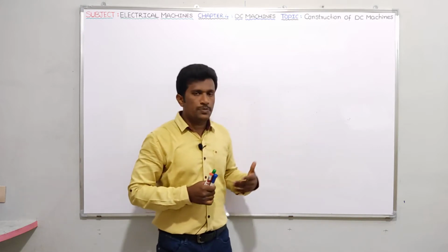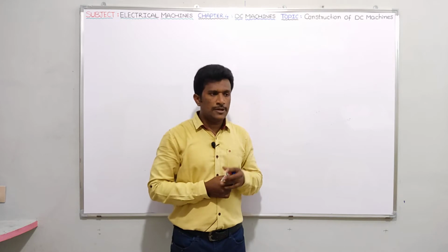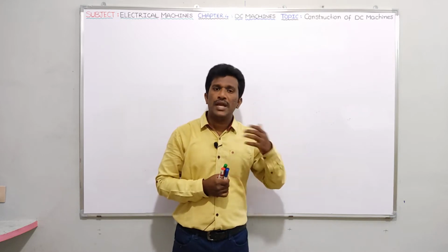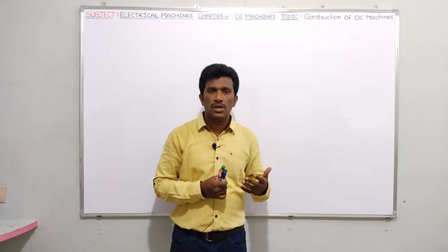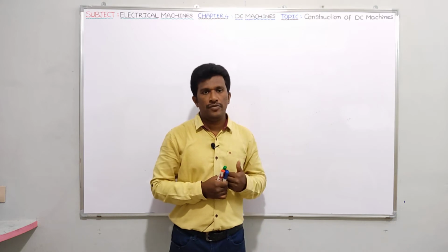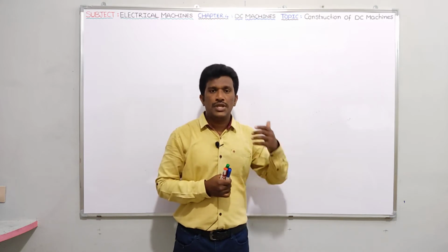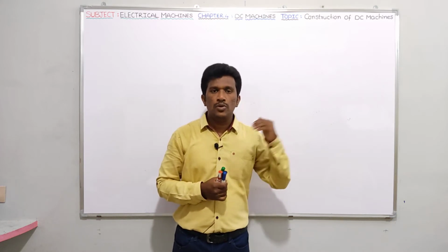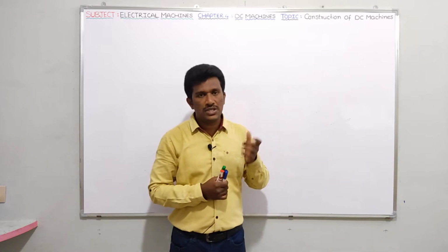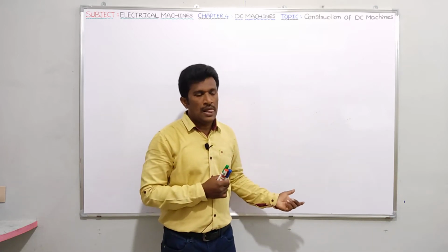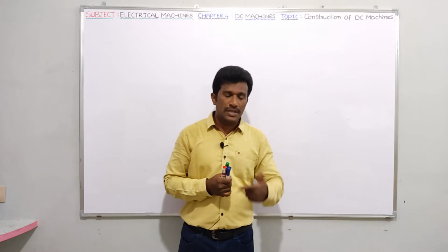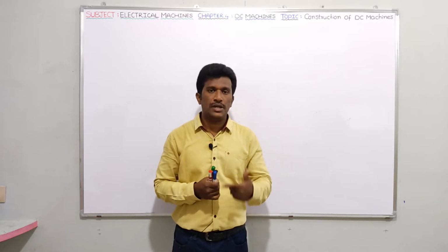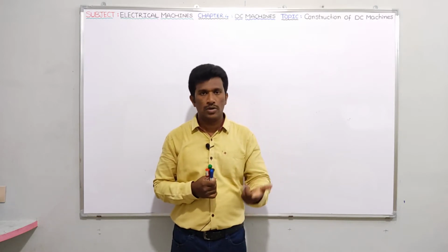In addition to these points, I told one more point. What is that? Commutator makes rotor MMF stationary with respect to stator MMF. This was the point I had given last. And I told that in the next video I am going to explain brushes and armature winding.